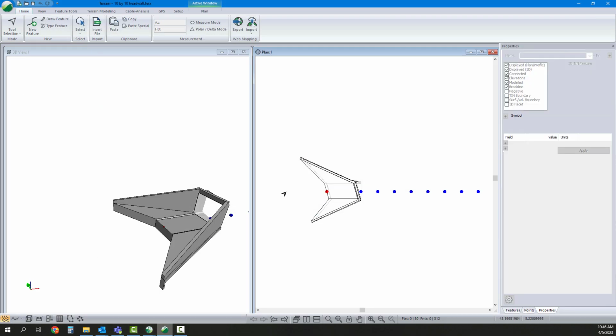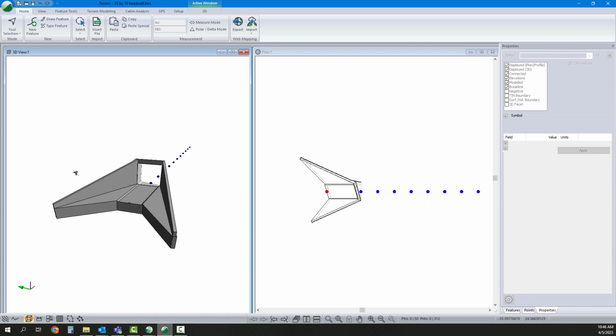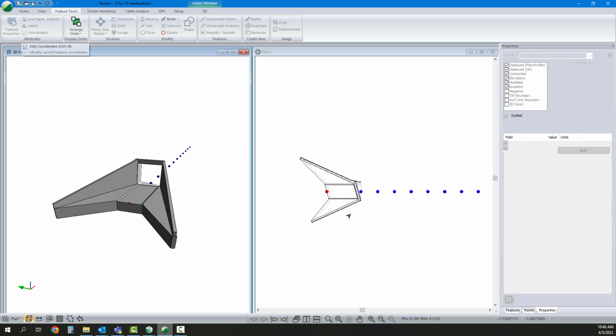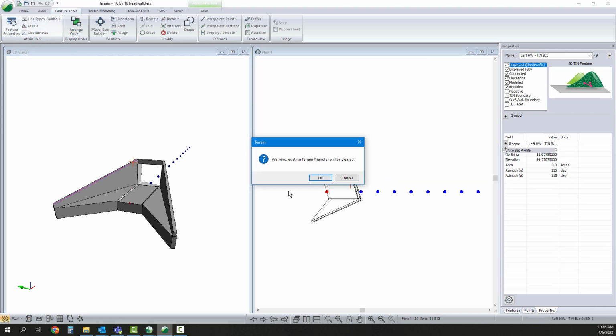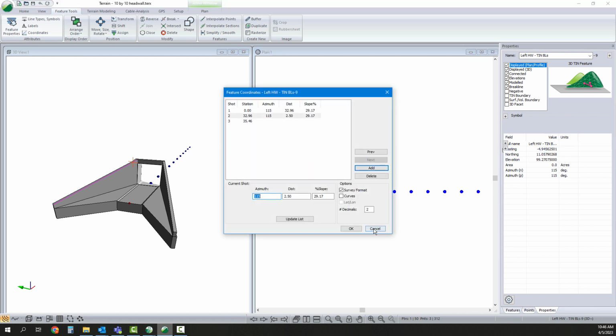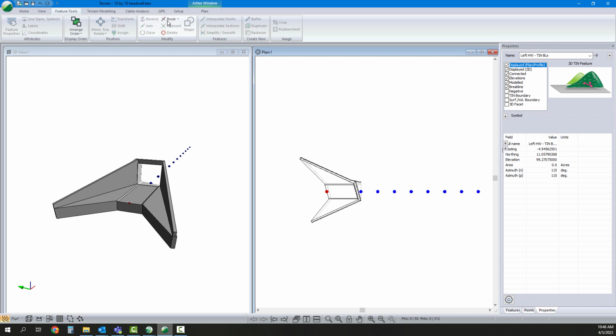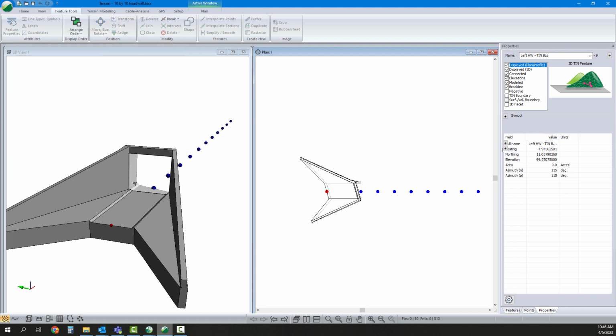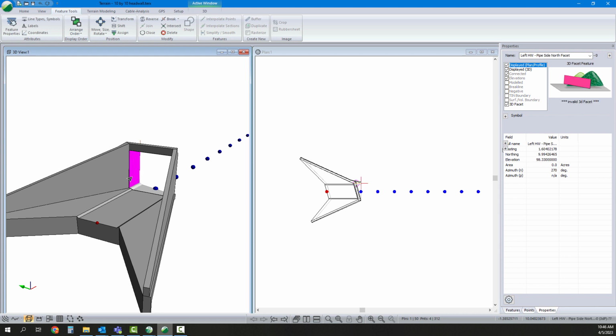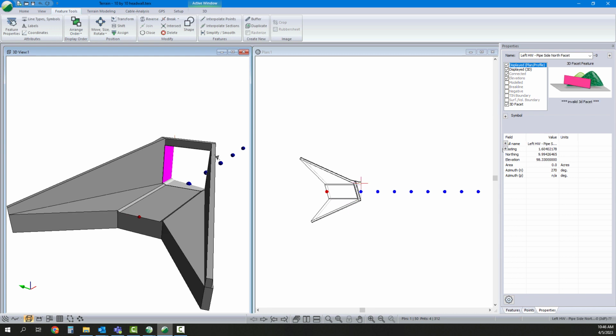And then we've also got a file prepared where we've got our head wall created. The main tools we've used to create this head wall are new feature, being able to edit the coordinates and enter the coordinates of different features tabularly, and using tools such as buffer, shift, and assign to get things positioned as we'd like. And I'll just mention too, the inside portions of these features are 3D facets, where the outside is designed as a tin. The outside top is designed as a tin.